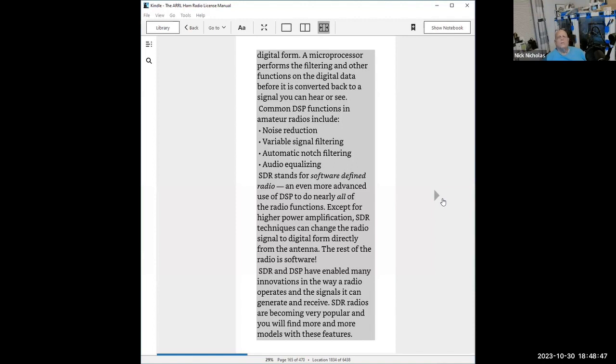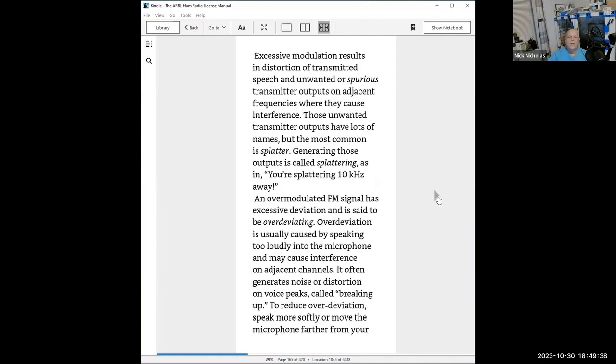SDR stands for software defined radio. Basically, that's what they are. They're radios built from microcontrollers, and the microcontroller actually builds everything, even the oscillators. The waveform is built in a microcontroller. It's pulses that are converted and made into an analog signal in the same digital to analog process. And it allows for some really, really cool radios, because we are now using far more stable microcontrollers than simple tune circuits of the past. So today, most radios are at least somewhere in between.